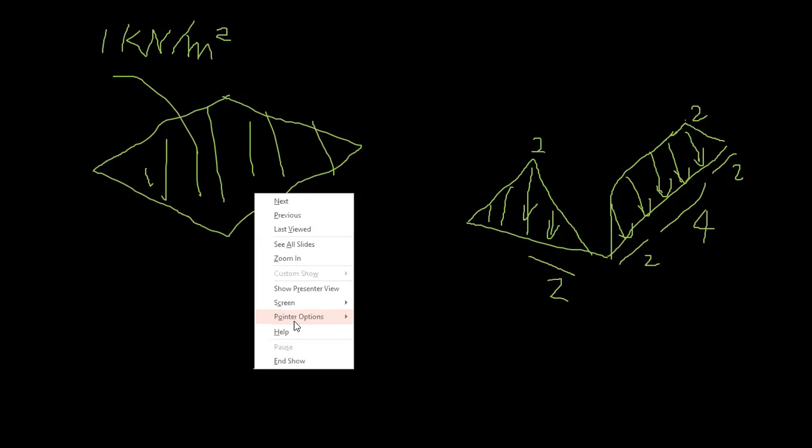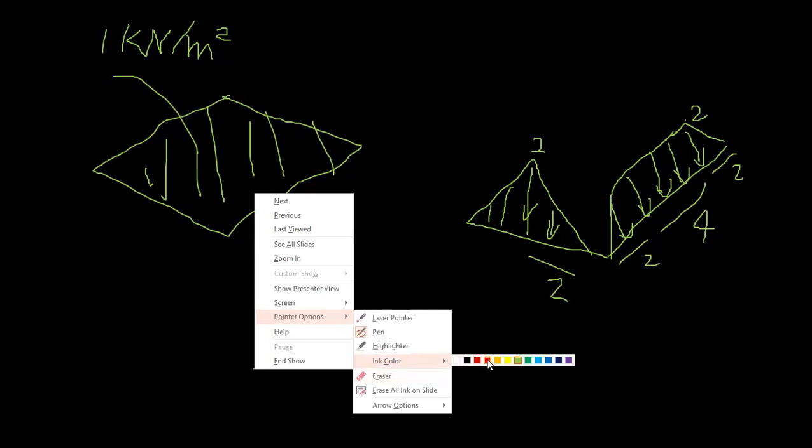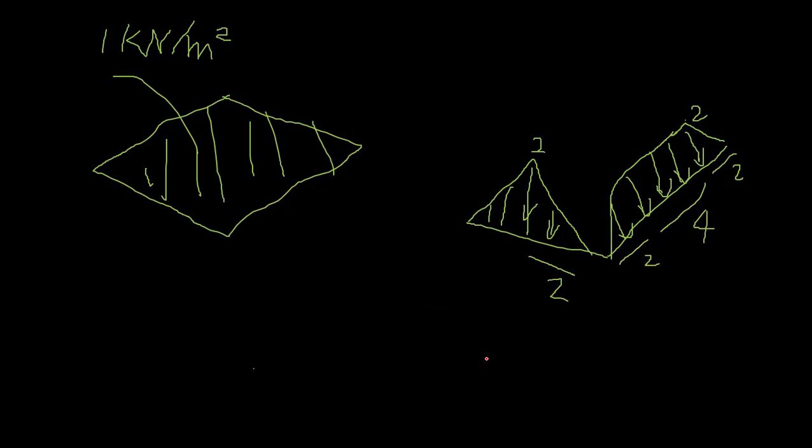So what happens if your unit live load is, let's say, 2.5 kilonewtons? You just need to multiply each by 2.5, right? So your live load is now added. These will be automatically multiplied by 2.5, and this UDL will be multiplied by 2.5. So that's the advantage of the unit load.